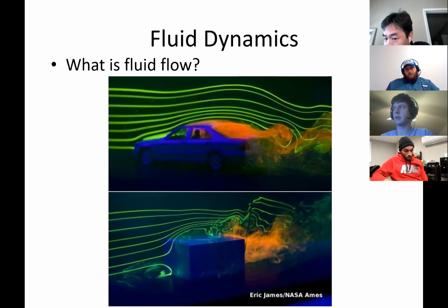Is the drag caused by the pressure difference between the front and the back? If the front has high pressure and the back has lower pressure, then you have a drag. The pressure difference pushes the car back. Since there's a smaller circulation region, you have a smaller pressure drop.